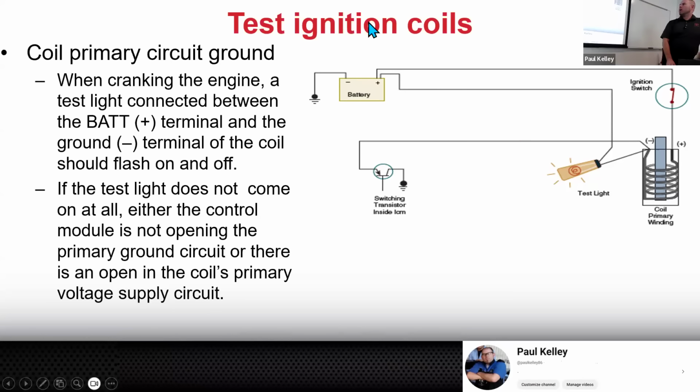So look, if we wanted to test it, and I do have a video that I added on testing ignition systems, all we really need to do is see if the coil is getting its negative pulse, right?